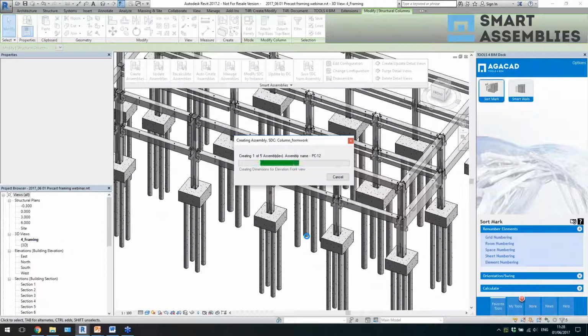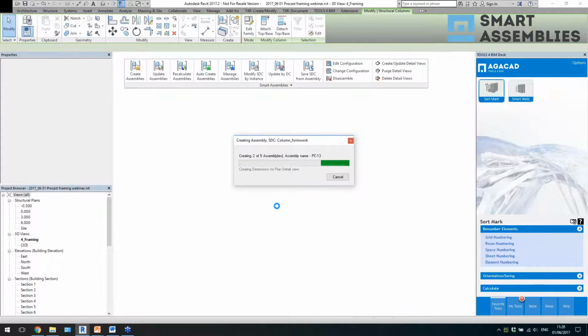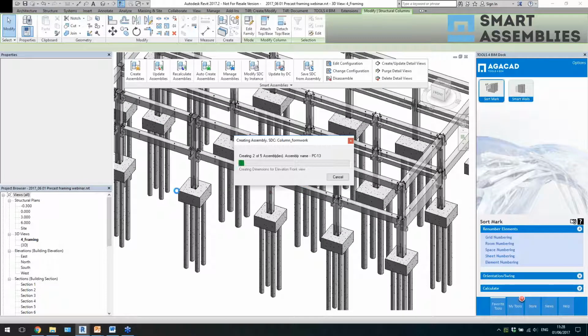So now it will use that sheet template in the template project, and it will place the views in the same order as in the template project. So actually this sheet could be in this file or in the template project, so it doesn't matter. It's just more time saving to have a template project. Okay, let's see.